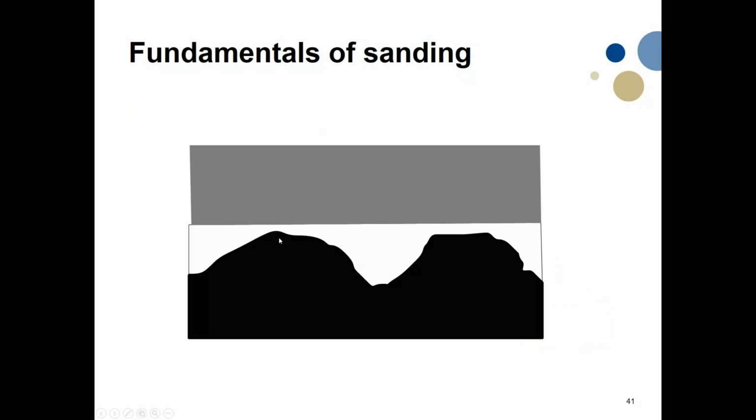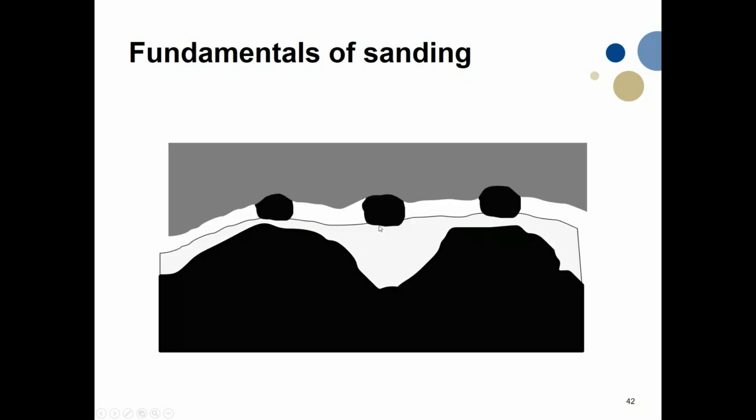But typically, if it starts to snow, and specifically if it starts to ice, we start to lose our roughness, or the roughness gets covered. And if there's still some roughness in the snow, we get some friction. If we don't have any roughness in the snow, then we get very little friction. So placing sand particles there is basically adding an extra medium, hard particles, whose main function is to concentrate the load into small, localized areas, so the sand particle can penetrate into the snow layer.